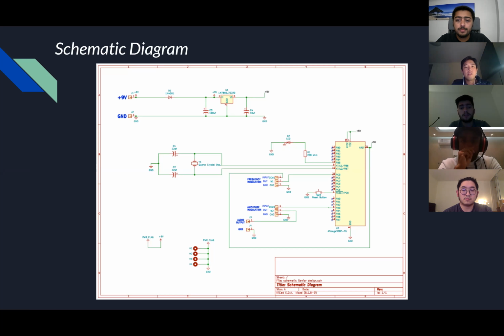And it is connected to a voltage regulator to make sure the voltage maintains its certain level and to adjust the voltage provided by the power supply and later inputted into the microcontroller. 2 capacitors with a capacitance of 100 microfarads and 10 microfarads are connected along in order to enhance the transient response to prevent the regulator from oscillation.